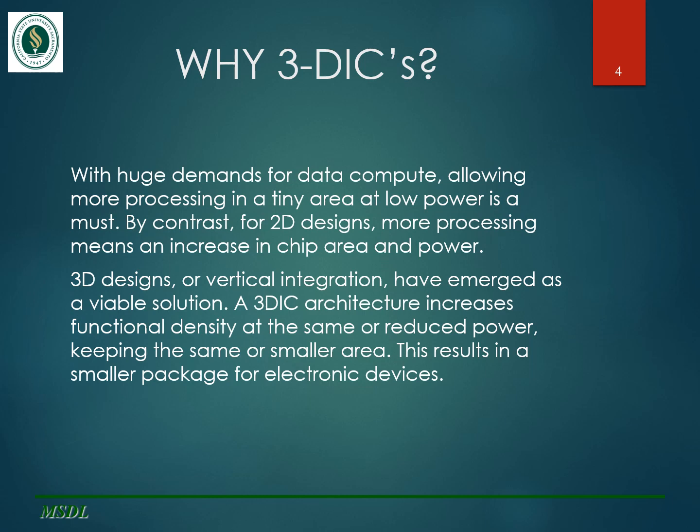Now, let's talk about the motivation of 3D IC. With a huge demand for data compute, allowing more processing in a tiny area at low power is a must. By contrast, for 2D designs, more processing means an increase in chip area and power. 3D designs or vertical integrations have emerged as viable solutions. A 3D IC architecture increases functional density at the same or reduced power, keeping the same or smaller area. This results in a smaller package for electronic devices.